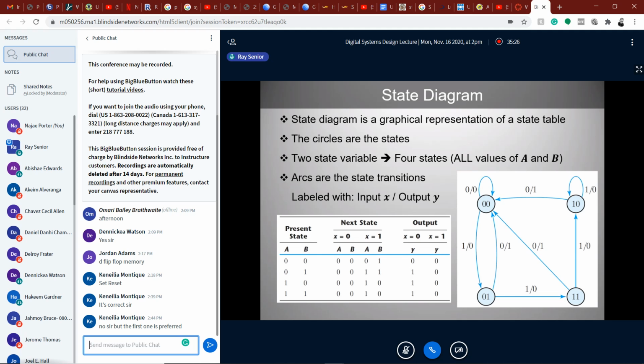And so on. So in this particular instance, let us start with that particular state, 0, 0. So if the present state is 0, 0, we are supposed to transition to a particular state depending on the input. Now, if the input is a 0, where do we transition to? If you notice, the edge really leaves from the 0, 0 state and it comes right back to the 0, 0 state. So it means that we remain in the same state. The output at that point is simply 0.